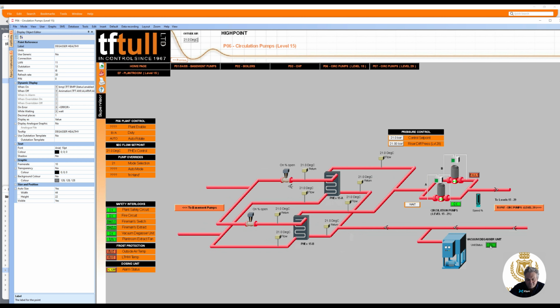Like a fire alarm, for example, if we look at fire circuit, false, which is what you would expect, isn't a fault. True is healthy and okay. So I can look at these and know what's true and what's false for the values. So when the engineer gets their commission and the graphics, most of it's all done for him. There's going to be the odd mistake, no one's perfect, but I try my best. So that's LAN 11 outstation 13, sensor 8.